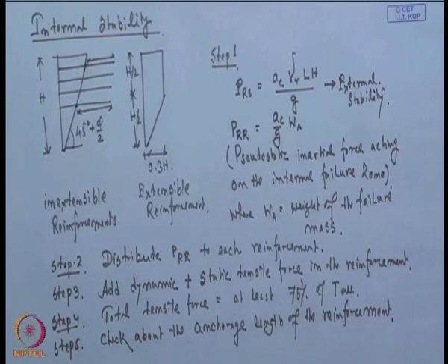So, now here we have to design this. If I consider the overall summary of this additional design, first we have to design it for the static condition. Then we will get an idea of the required length, and we can use that for our first trial condition: what would be the length of the reinforcement and what is the height and spacing. Based on that we will determine the area of the reinforced zone. Then there will be two different densities, one in the reinforced zone, another outside the reinforced zone. Once we get the reinforced zone, based on that we will calculate the inertial force within the